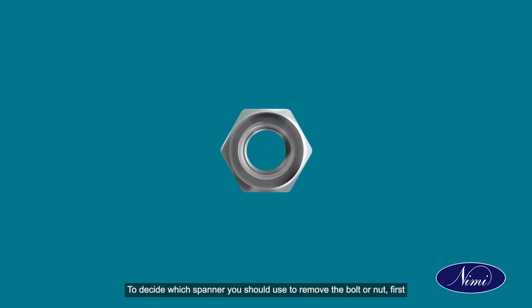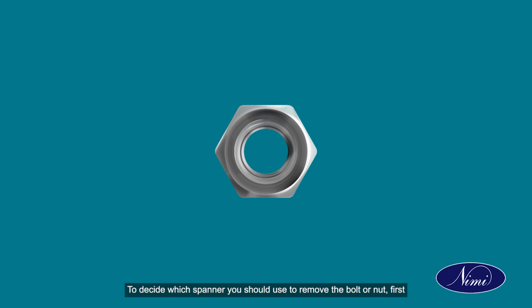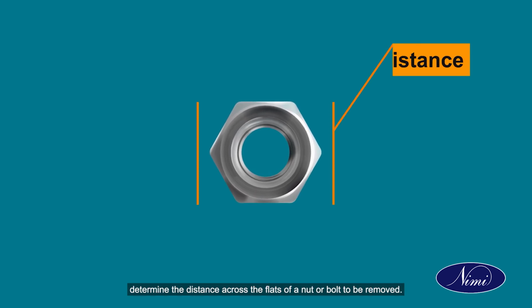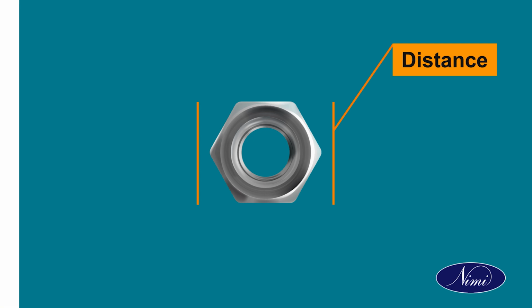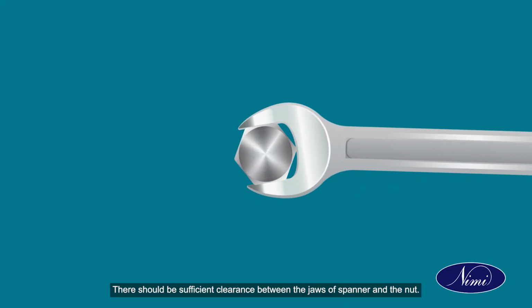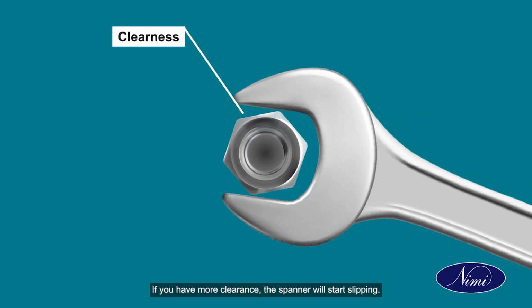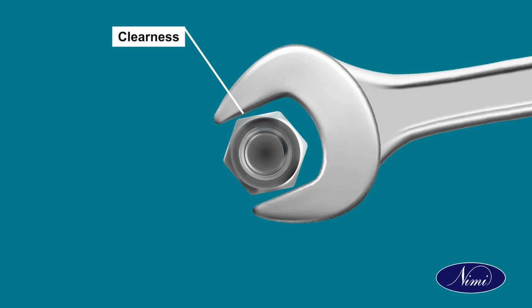To decide which spanner you should use to remove the bolt or nut, first determine the distance across the flats of the nut or bolt to be removed. There should be sufficient clearance between the jaws of the spanner and the nut. If you have more clearance, the spanner will start slipping. Select the correct size of the socket.